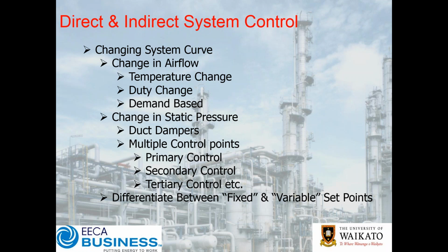And typically in a lot of manual applications like that, it's something that you'll set and then forget, and won't actually then be continually controlling actively that set point. So when you're looking at a system, it's very, very important to stop and ask the question: is this control valve, be it a damper, a butterfly, a knife, whatever it is, something that is locked in once I tune my system and then left in place, or is it something that's being actively controlled?